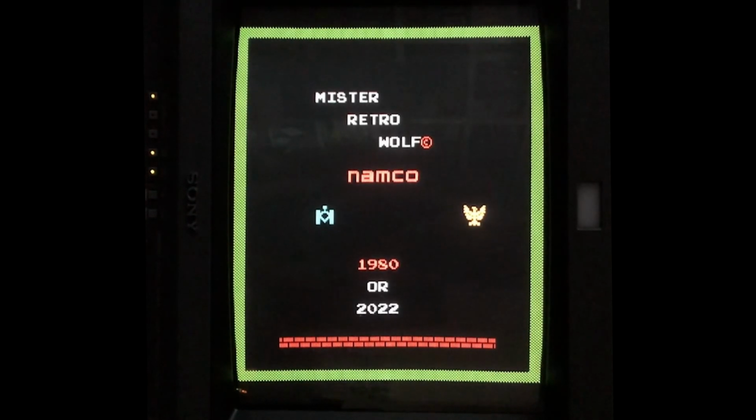So there we go, we've got the ROM there showing the screen that we created, and it shows that we can just put characters into the ROM and it's going to get the video display side of the circuit just showing whatever we want there. Now imagine if that, instead of being ROM, was a RAM buffer, and then we're writing to that RAM buffer. That's obviously how we then get that to change in real time on the screen. So that's what we're going to look at in the next hardware episode, how we can do that.